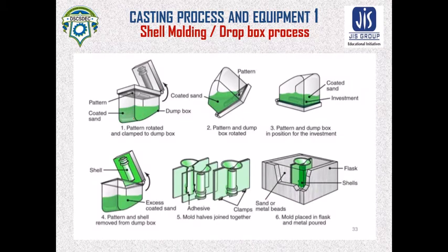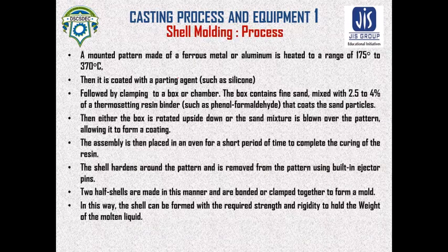Then it is placed in a box. It is clamped in a box or chamber. The box contains fine sand mixed with 2.5 to 4% of thermosetting resin binders, and this coats the sand particles. That means the box contains coated sand.